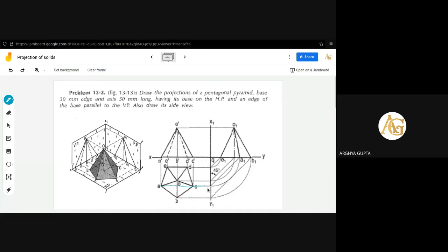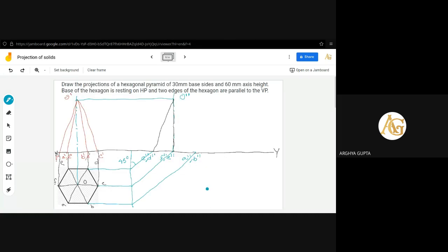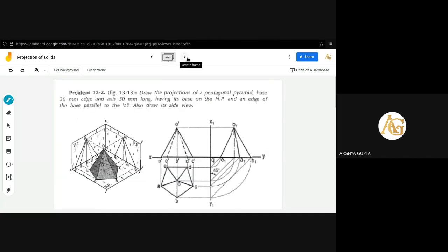Now you have to decide through which point you will take the axis height. So projection of O. So you need to draw 4 45 degree lines. One from O1, from C another, and from B another. Okay. So the 45 degree line drawn from O is this one. So from this point, you need to take the axis height. Okay, and so for the side view, the observer is viewing from this side.